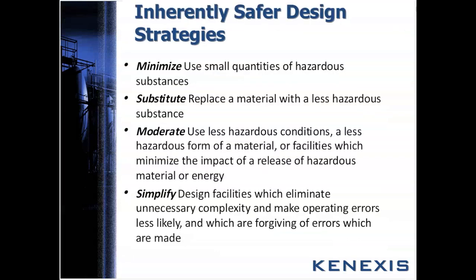Inherently safer design strategies checklist. Now, keep in mind, chemicals by their very nature may be hazardous. The hazard's intrinsic to the material. Chlorine's toxic. Sulfuric acid is very corrosive to skin. Ethylene's very flammable. Acrylic acid, or any monomer, could polymerize or release large amounts of heat. Steam confined in a drum at 600 psig contains a significant amount of potential energy. So you can't change an intrinsic property of a chemical, but you can use these strategies to reduce risk.